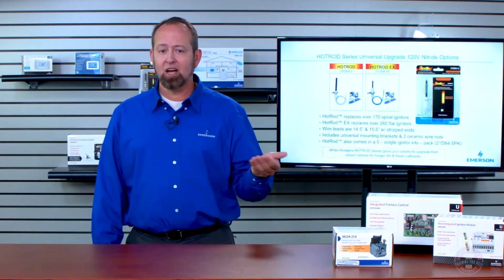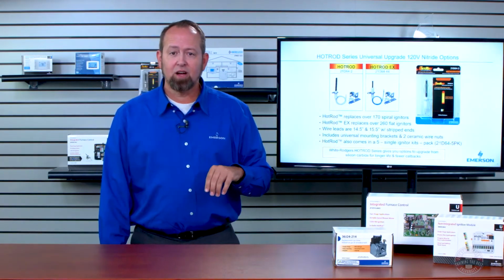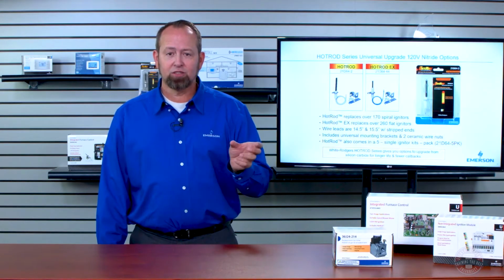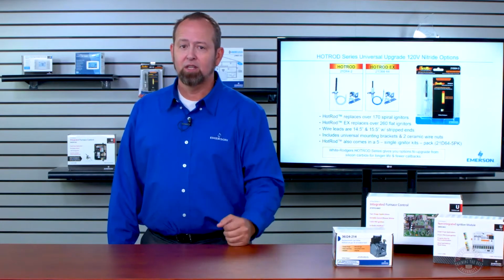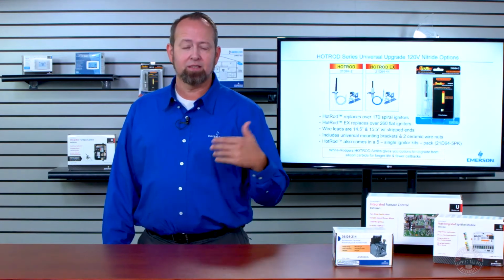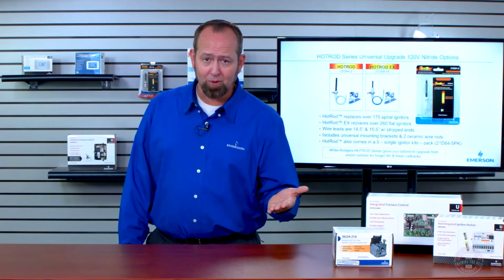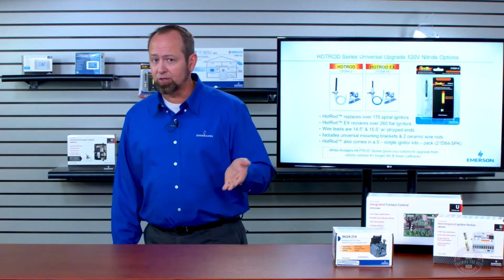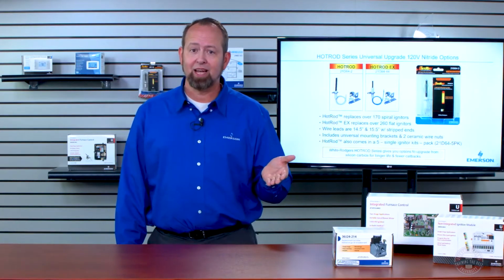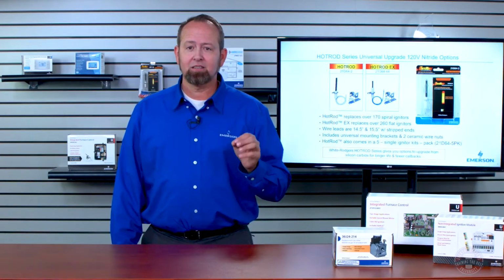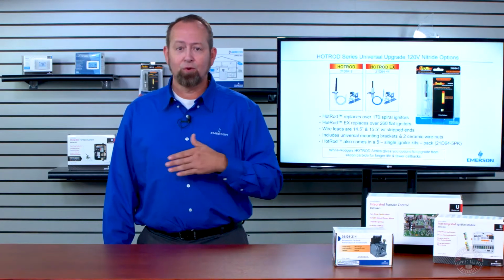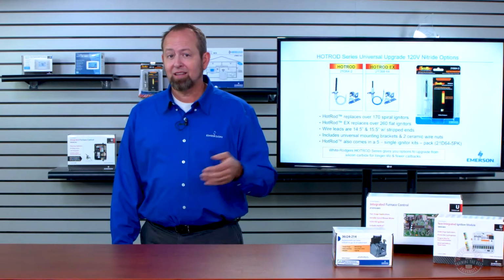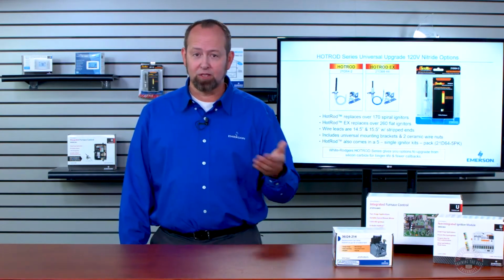That design does not cross over to the hot rod, which has a larger size and a larger base. Typically on these you can have the 17-second normal warm-up time all the way up to the 34-second that some controls have, and the silicon nitride can handle being on for that whole amount of time, and it's not going to affect its length of life or its operation.